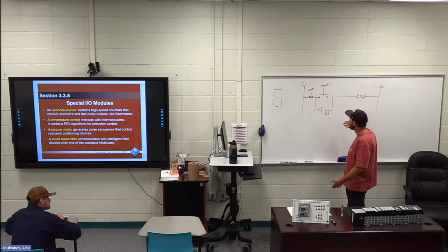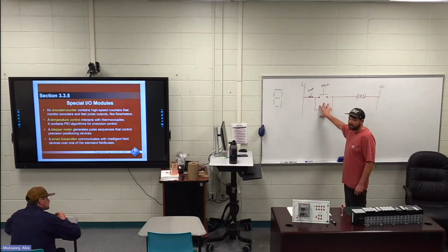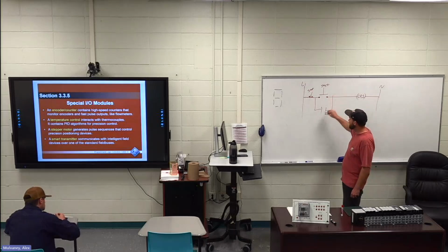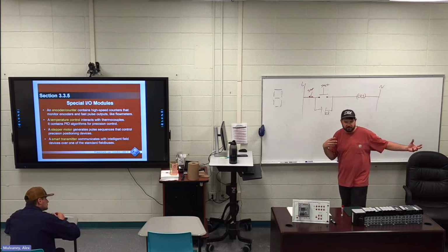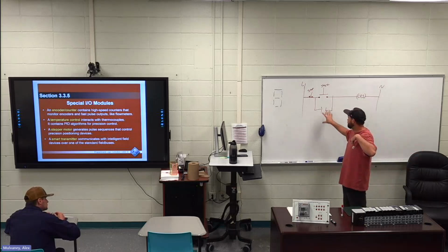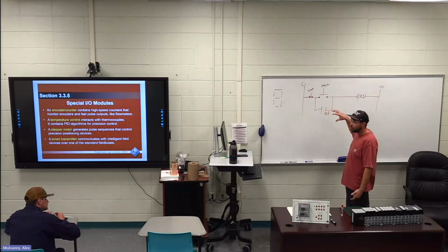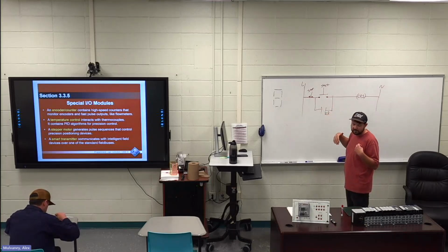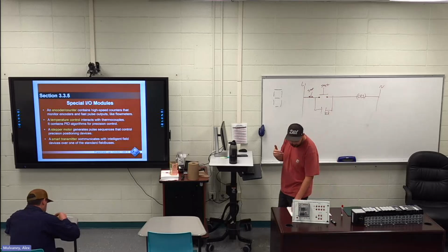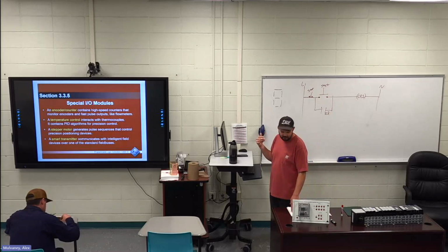A language gives you, say, a normally open contact, and then you ask what's the address of that contact? I pull from a list of stuff I put in my inputs, a light switch or whatever it is, and I put it on that contact. They created that for old school electricians, but that's all I've ever used. That's mostly all I've ever seen or used, ladder diagram, LD. This is a dumb question, but it will be on the quiz and on the test.